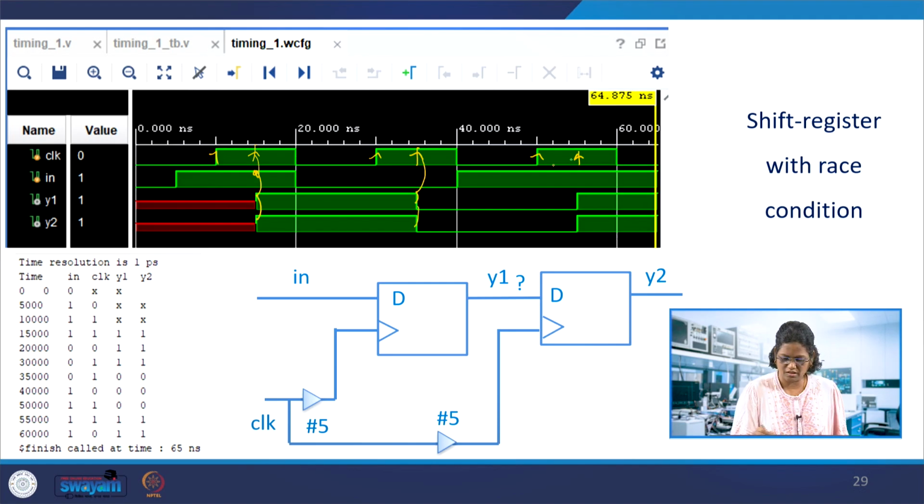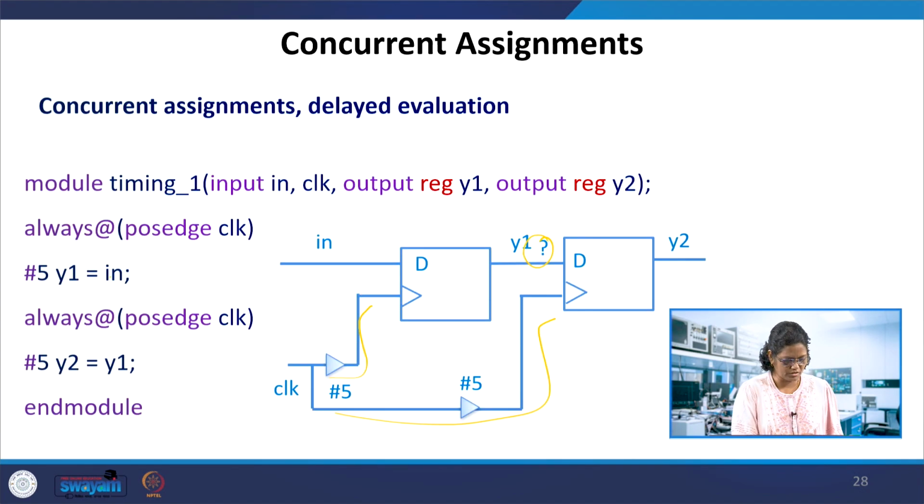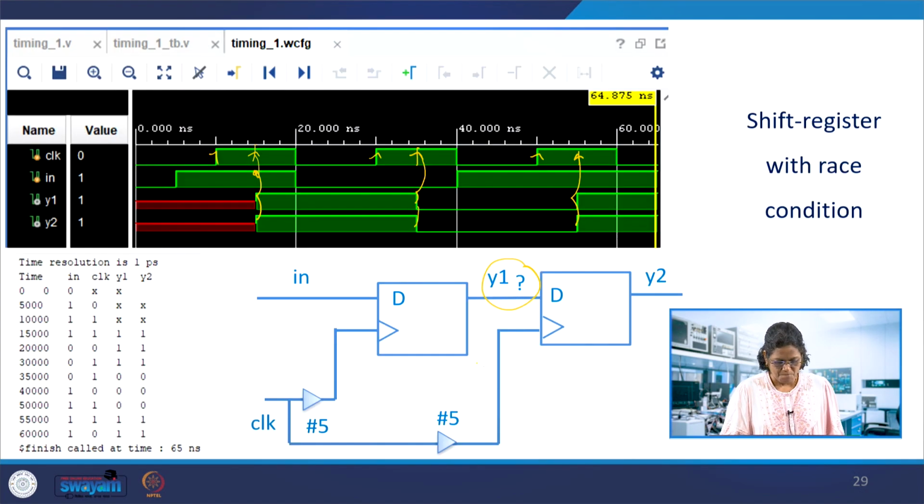It gives that parallel condition. So this would definitely be an indeterminate result in the hardware. It forms the race condition in this case, because of the immediate assignments. That would create confusion in the realization. So, noting down that delayed evaluation can be looked at as delayed clocks.